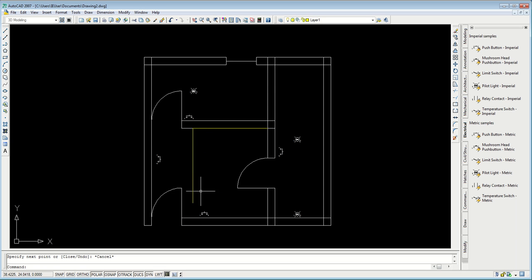So here, for example, I will take this dimension to the center. Okay, so this dimension is 24, so here I will reduce it by 12. So this is the center of this room. So I will take this one and copy paste here. So now I have one lamp here. Yes, so I have one switch here, two lamps, one switch here, one lamp, two switches here, and one lamp.